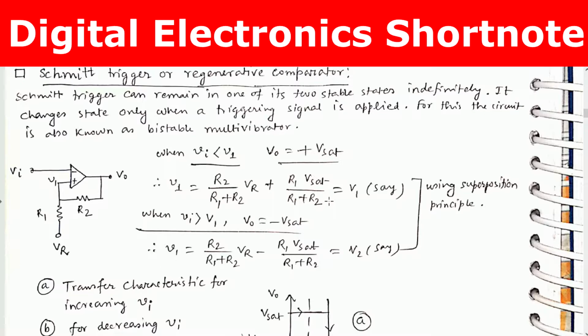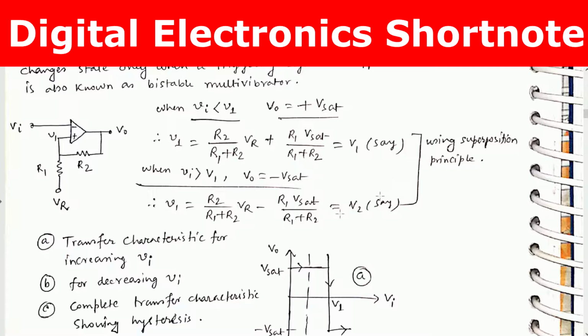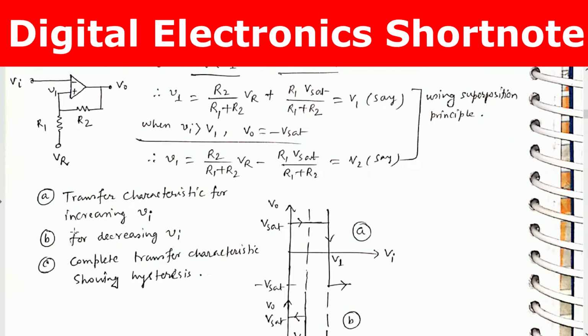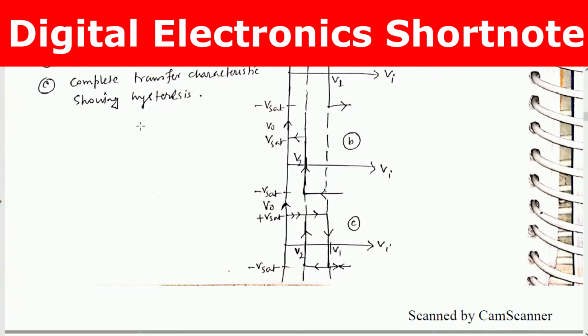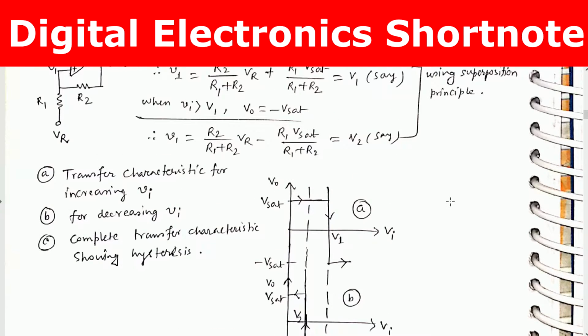Now what we are doing, we are just trying to calculate the output voltage, and that's why we are using the superposition principle. So using the superposition principle, we can find out the output voltage. Now this figure A shows the transfer characteristics for increasing Vi, and B for decreasing Vi, and C is the complete transfer characteristics showing hysteresis.